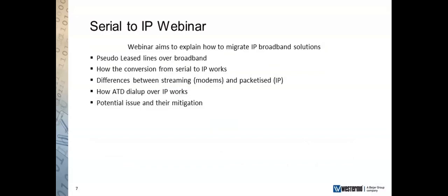How the conversion from serial to IP actually works, and why sometimes the differences can cause a few issues, and how to get around those issues. Basically, we're going to be talking about the difference between streaming, which is the way the modems work, and packetized data, which is the way IP works, and hopefully give you an appreciation of why there are some differences between the timings and how things actually work, and how it can work to your advantage in the future.